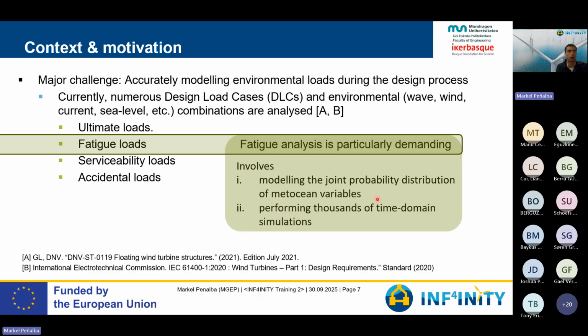You will see afterwards that current is sometimes neglected, and even the standards, and not only the standards, even other white papers or reference documents suggest to neglect the effect of the current when analyzing fatigue loads. But this involves performing thousands of simulations. And when I say thousands, if you combine all the different possible scenarios or conditions, wave, wind, current, then it results in tens or hundreds of thousands of simulations, which is unfeasible or prohibited in terms of computational cost.